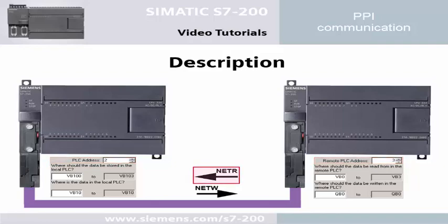Using the Net R function enables reading a data area from a remote PLC and storing it in a selected data area of the local PLC. Using the Net W function enables writing a data area from the local PLC into a selected data area of a remote PLC. This enables communicating with up to 24 PLCs per port via the instruction wizard for Net R, Net W.